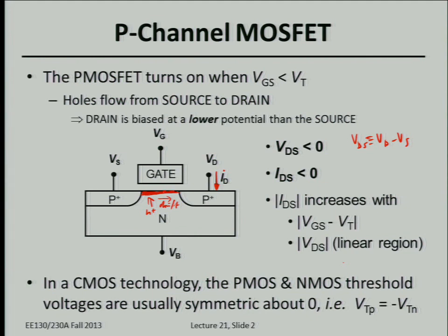So that means that, just according to this convention, drain current for a P-channel device is negative. Okay, it's just because of this definition, this convention. But just like in an N-channel MOSFET, if you increase the difference between the gate voltage and the threshold voltage to invert the surface more and more, you'll get more and more inversion layer charge density at the surface, so you have more current. The magnitude of current will increase.